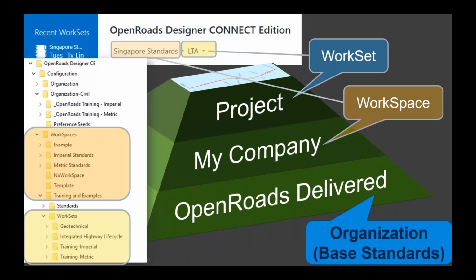ORD does not store its standards in one template file like other civil softwares, which is the main reason why file sizes becomes heavier and heavier as you progress with your project. So this workspace workset methodology can then be set as the standard in your organization, regardless of what project you are doing. Now, the beauty of this kind of technology is that it enables flexibility no matter how big or small your team is, or even your project. It can easily be shared within your organization, and together with the federated technique of file management, it optimizes your file sizes and allows for bigger or larger models to be created in the long run. So that's the third point.